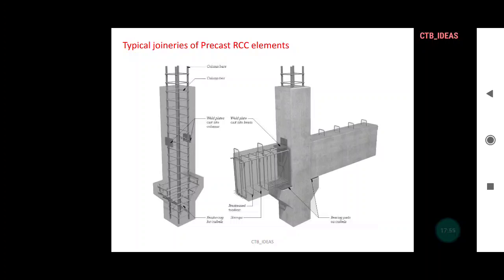Those two metal plates, the upper part of the corbel and the lower part of that beam, are going to overlap on each other at the base, and at the top you have the metal plate at the side of the column and the metal plate at the top part of the beam. Having placed the beam at its place, you have to use an angle section or an angle shaped cleat, which is welded on that particular part. At this part, the angle shaped cleat is to be welded.